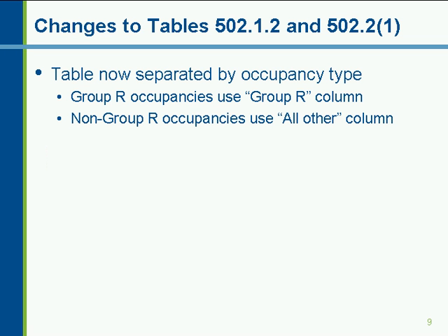The primary reason this was put into the code is that the energy used for high-rise residential looks a lot like what a low-rise residential multifamily building would look like. In other words, we live in that building during the evening time and we're out of that building during the daytime. For commercial buildings, we're typically in the building during the afternoon and morning hours, but we're not in it during the evening time. So the energy schedules for both those buildings are different, and it was actually fairly cost-effective to increase the insulation requirements for high-rise residential buildings. So this was a major submission into the code.